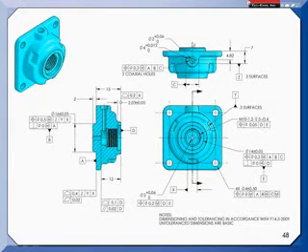So when we look at the actual drawing, first let me point out that we've brought those cast datum features over to the machining print. So it's all tied together, it's all connected. Then I have located this primary datum feature from my cast datum features, and I've tightened up the form of it. I don't want it rocking around, or it may be a sealing surface. Then I located datum feature B, this pilot, on that casting, positioned to ZYX, and then I've tightened up its perpendicularity to A.